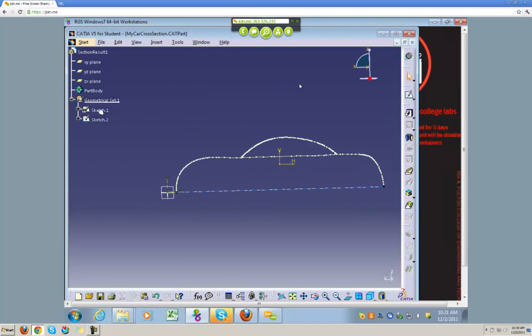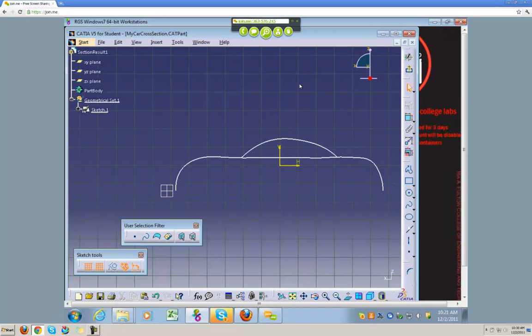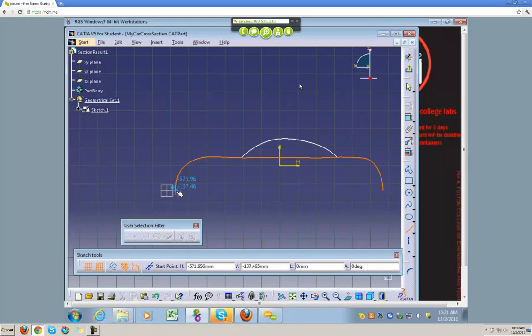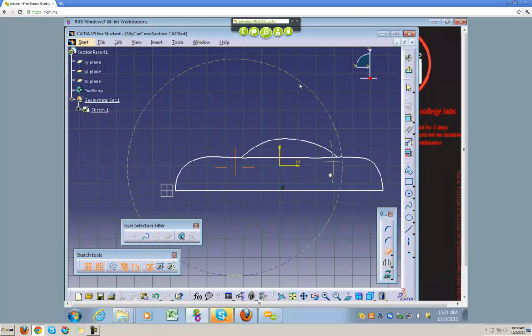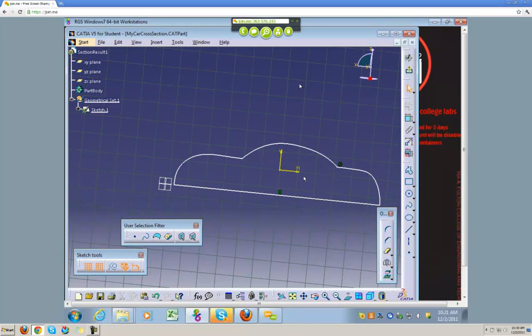We're also going to go back into the first sketch. Oh, actually, no, hang on. You just go into the first sketch, sorry. Go into the first sketch and draw the line so it's all in the same sketch. So once you got your line across the bottom of your vehicle, you want to trim out this line here on the interior. So we'll just bring up our trim tool. And we'll click on this line, and it'll just remove everything. Okay?